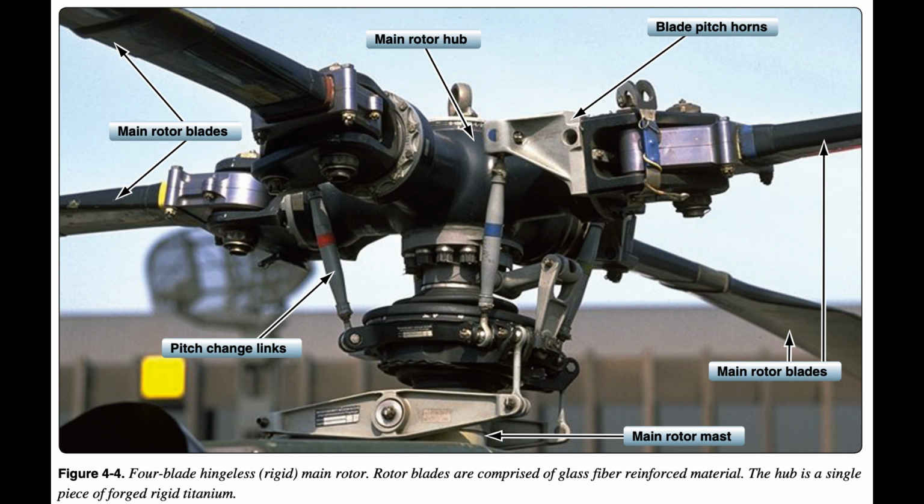Rigid rotor systems tend to behave like fully articulated systems through aerodynamics, but lack flapping or lead/lag hinges. Instead, the blades accommodate these motions by bending. They cannot flap or lead/lag, but they can be feathered. As advancements in helicopter aerodynamics and materials continue to improve, rigid rotor systems may become more common because the system is fundamentally easier to design and offers the best properties of both semi-rigid and fully articulated systems.